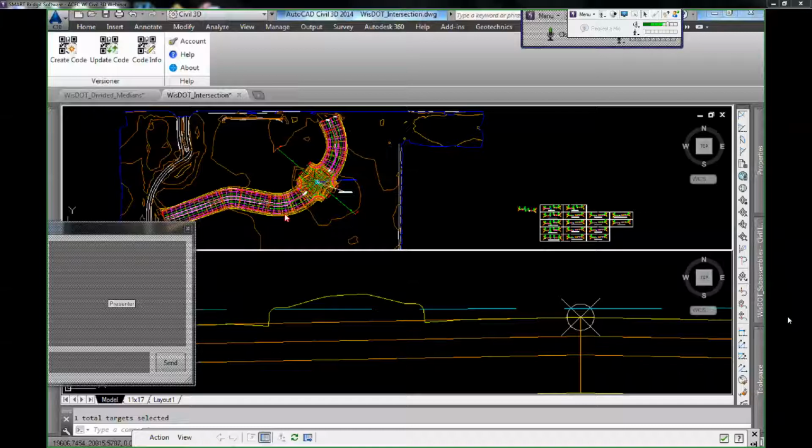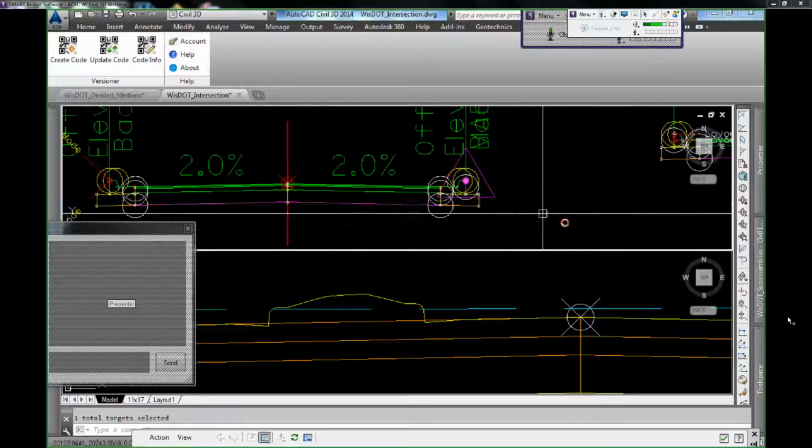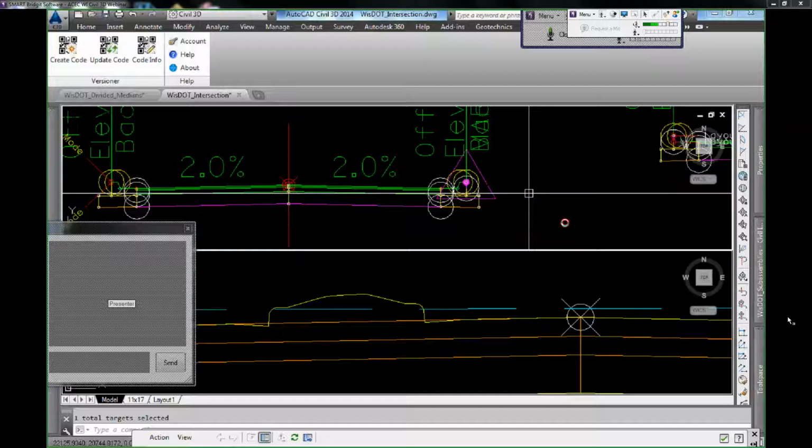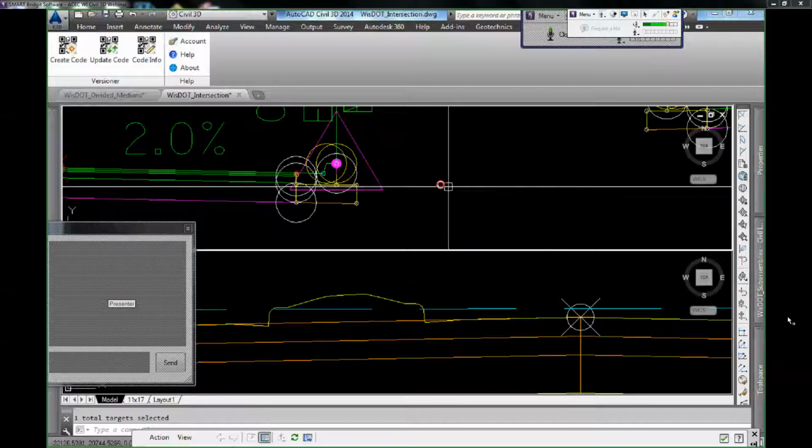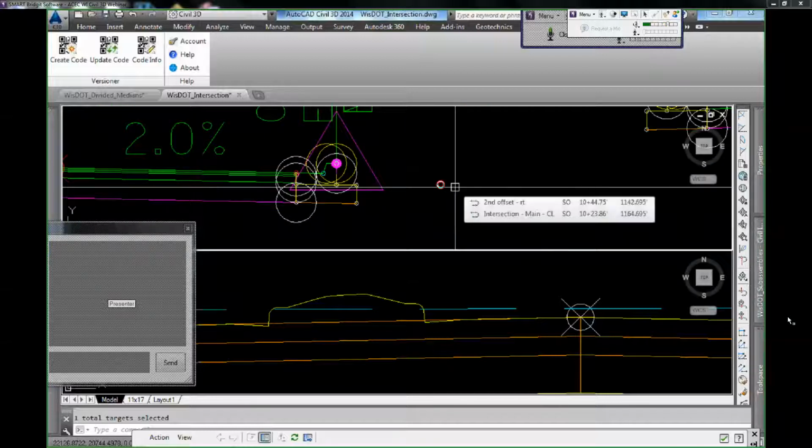And so what we recommend people doing, we do have some of those problems, especially with our curb subassemblies and some of the other subassemblies that have vertical or near vertical link components to them. We use just a generic link and we create an additional corridor feature line, maybe 1/100 of a foot offset from the vertical, either on the top or on the bottom, and then we use that one that's offset 1/100 of a foot in our surface definition, rather than using the default corridor feature line link that the subassembly creates.